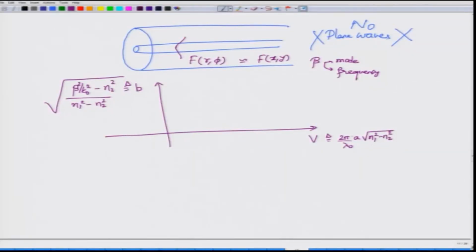to frequency, because 1 by lambda is proportional to frequency, for different modes, you see these types of curves where B max is about 1 and it is reached asymptotically. You have seen these kinds of graphs. So, this corresponds to the LP01 mode. This group essentially corresponds to the LP11 mode or LP02 mode. I forget that exact one, because normally I deal with only single mode fibers.